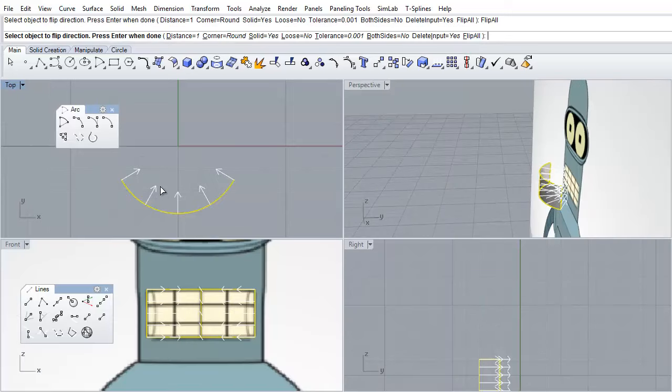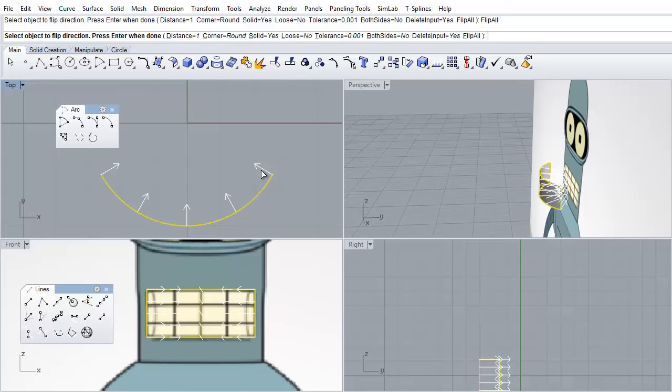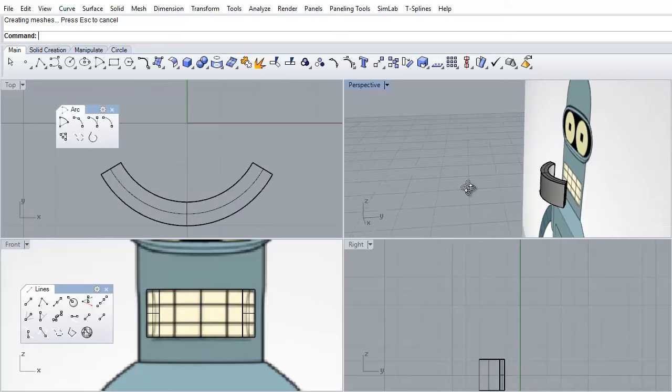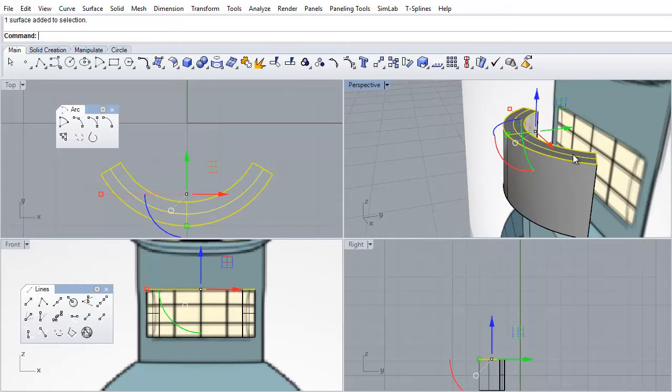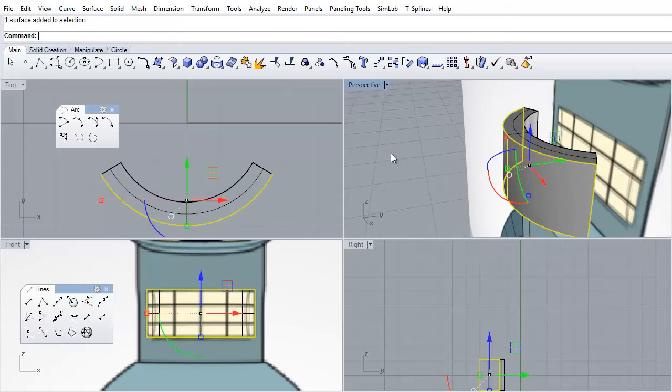Alright, let's look in the top down. I want it to go in about that much. It's about a 0.5 millimeter, I guess, 0.7. Okay, and we're now going to explode it. You can either type explode or you can use the explode thing up there. What that does, it takes a solid and it turns it back into its component parts. We want to delete the front part.